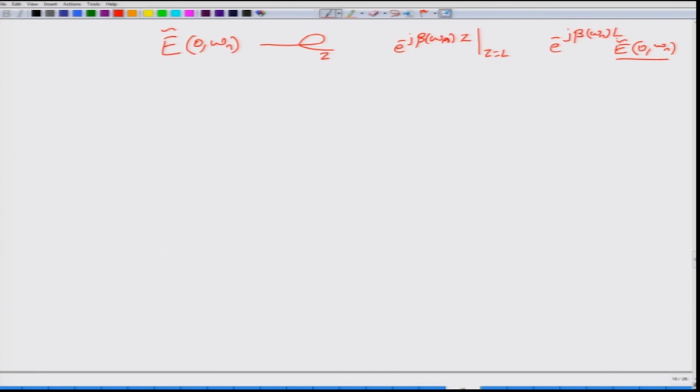If you are not really convinced by this, think of, say, y polarized light propagating through free space for a certain distance z. After propagation you would have written this as e power minus j beta z, where you would have assumed beta to be the propagation constant, independent of the frequency. So, in the free space case, beta would be given by omega square root mu 0 epsilon 0, or equally omega by Vph, where Vph is the phase velocity. You would have assumed this.